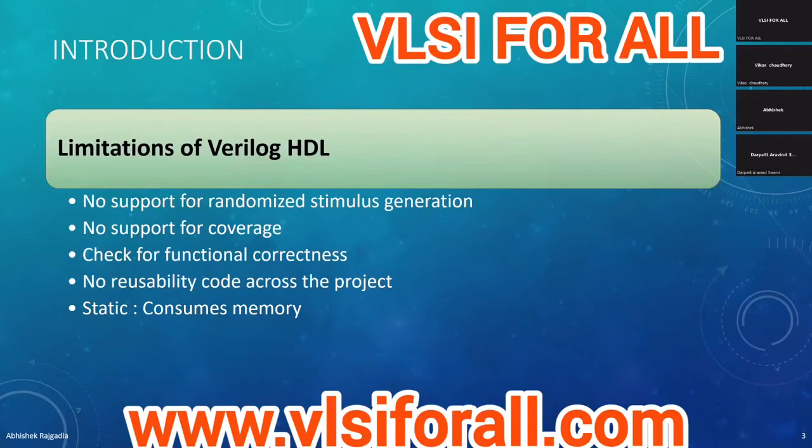Verification was not so complex earlier because the complexity of the design was low, and the test cases required to test that design didn't require so many scenarios or so many stimuli. We call this stimulus from the System Verilog or the UVM perspective. The stimulus is basically what we give as input to the design to verify a certain use case. Since the design was not complex, we didn't require as complex a test bench, and it was easy to code those low complexity test benches in Verilog or VHDL.